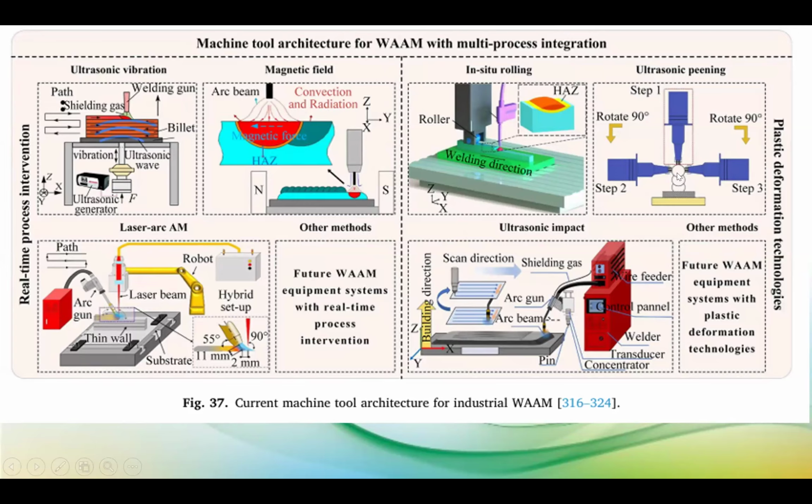So even if you are using two solid wires, definitely both will melt and go to the substrate, but we may not be able to control the exact composition by this method. So it is a basic thing. You can use one more additional wire for printing of multiple materials, which will enable this WAM process for printing alloys and composites.